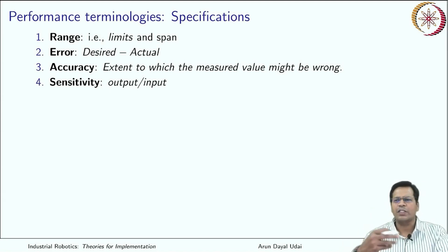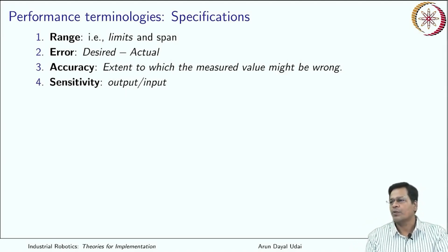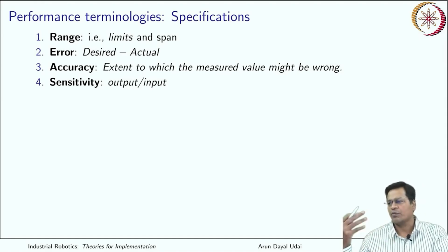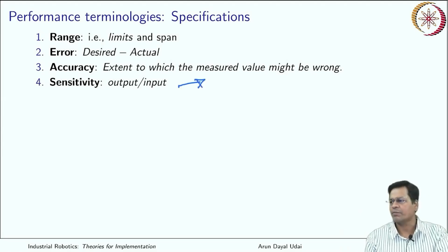So it is naturally sometimes damped to make that happen. Sensitivity is the output versus the input. Okay, so the input is the signal which is coming, and the output is the actual value that it should show, depending on how they are calibrated. So yes, it is sometimes digitally controlled, or sometimes it is a property of your system in the case of mechanical sensors.